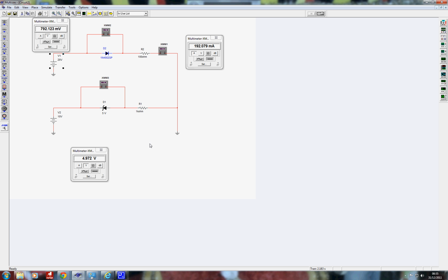They are supposed to switch on, they're supposed to conduct, but to maintain a voltage across themselves, which in this case, for this particular Zener, is given as 5 volts. There's many different types of Zeners, and they can have different voltages, but this one should maintain 5 volts across itself, regardless of what we do with this power supply here.